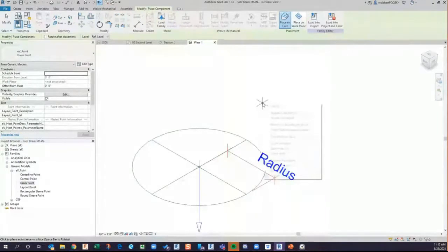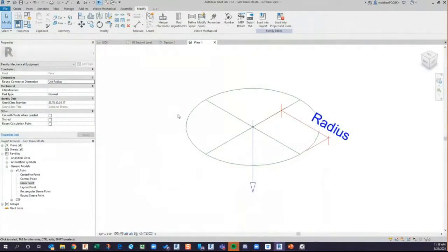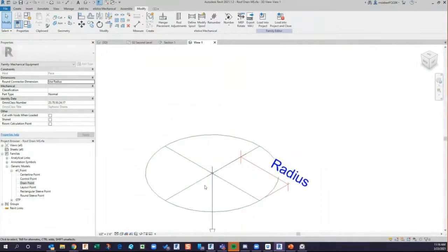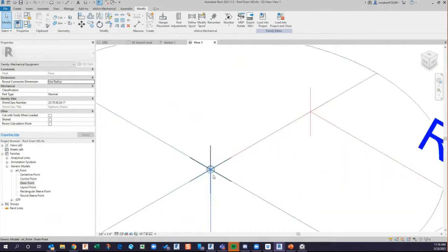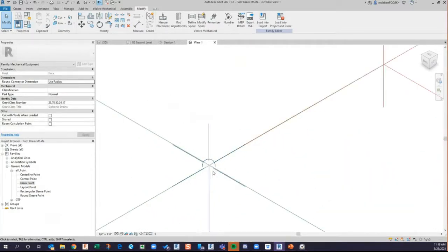Then, after I'm done setting the point, now I have to make the parameters for this point, okay? It's important. All we've done is set an image to show where the point is. So we're going to come in here and we're actually going to look at creating a shared parameter that this point will read.